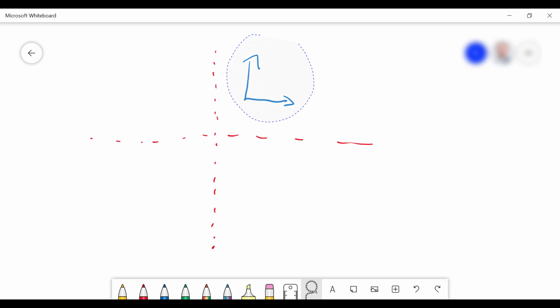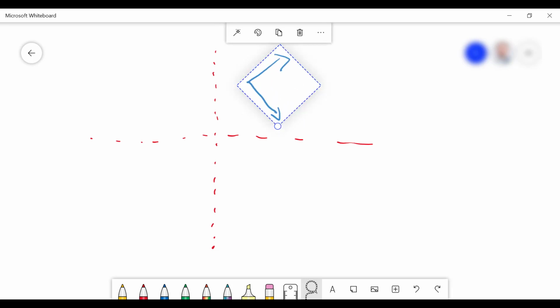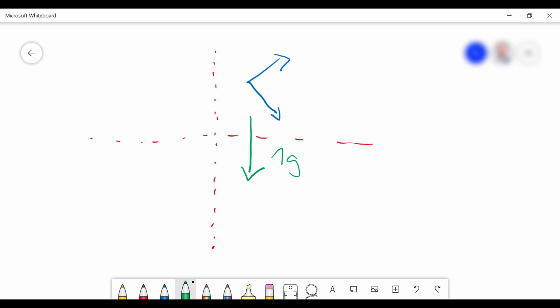So we rotate our system about the z-axis, even if this is not drawn here. And let's take an angle of about 45 degrees. What would happen now? The gravity, of course, doesn't change. So we have it in the same direction. And this g will now split. The y-axis, so the element which is measuring gravity in the y direction, will still get a reading, but now also the x-axis gets a reading, and both would get a reading of, let's say, -0.5 for y and 0.5 for the x-axis, and this can be calculated to the 45 degrees now if we do some trigonometry.